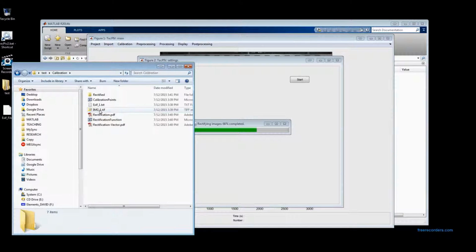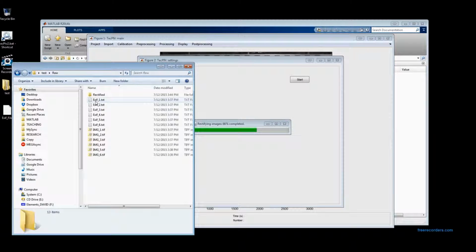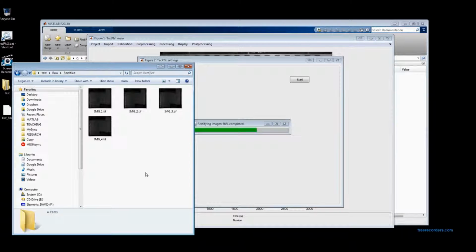Alright, so this is our image. Now, before we do the correlation, we can adjust the contrast on this image. We want to use this distribution of particles at the surface of the model to identify each image sub area and see how much it moved. So we're going to adjust the contrast to see these particles even better. So I'm going to inverse this image, subtract the background, using a Gaussian curve with the parameter 50 and 10. Now we start. This is what we obtain, and that is good enough to calculate the vectors in the center in this area.